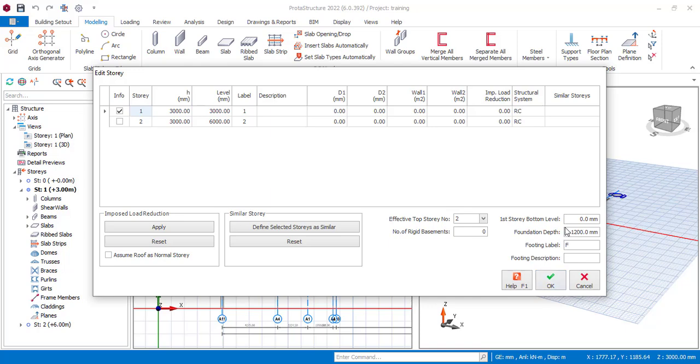Okay, and then here you can specify the height of your story. Mind you, the story height is actually based on the architectural drawing. So when you look at the elevation or maybe the cross section, it will be able to tell you what the height of that building is. But you know, for most residential buildings, except in special cases, the height is always 3 meters. So it varies based on the design.